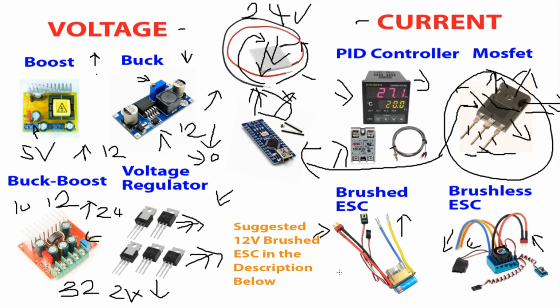So coming back to 2 wires and the brushed speed controller, this can't work by itself. It needs a servo tester, which plugs into the servo, and you can buy one of those for like $2. Then, sure enough, you can control the power going to your TEC with one of these and a servo tester. Done, and it will work.